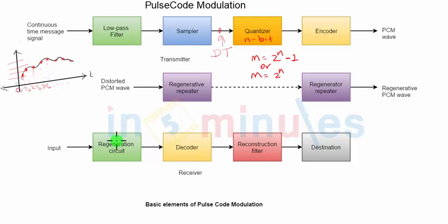And hence, we take advantage of the very simple nature of the digital signal and we place regenerative repeaters. The function of these repeaters will be nothing but to send the attenuated voltage level back to its original value. I'll give you a simple example in which it can be done.